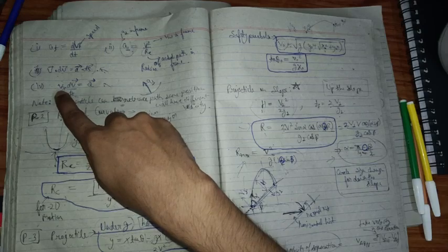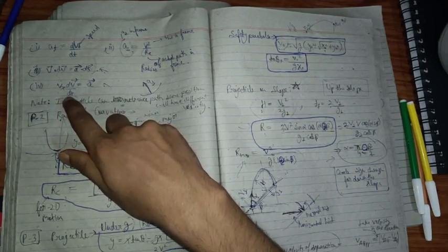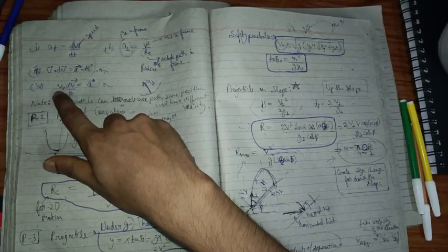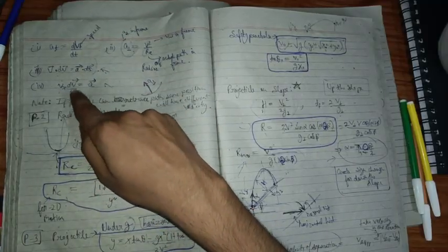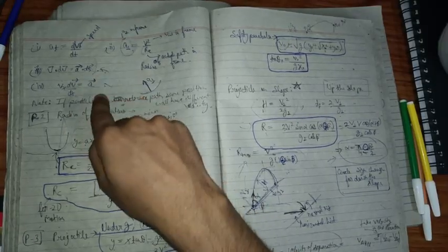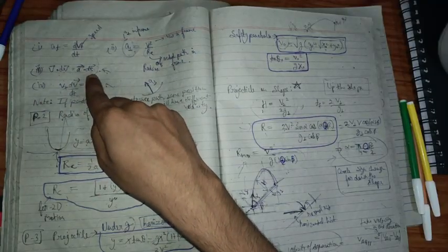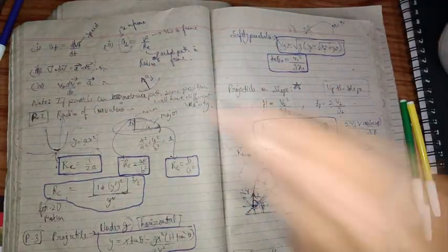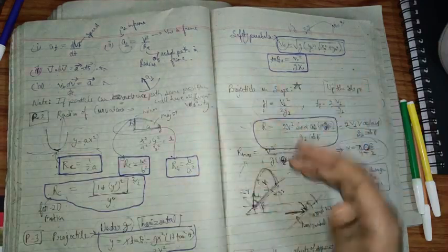Here this is not total velocity, it is the velocity along a particular direction. If it is dx, then it is the velocity along the x direction. If it is dy, then it is the velocity along the y direction. We cannot divide by a vector quantity, that's why I am taking only a particular direction displacement. But if I write it in this form, then I can take the total vector, which is v dot dv equals a dot ds. But if I take the ds, which is a vector, in the denominator, it is not possible. That's why we take only dx, dy or dz in the denominator, not the total vector.